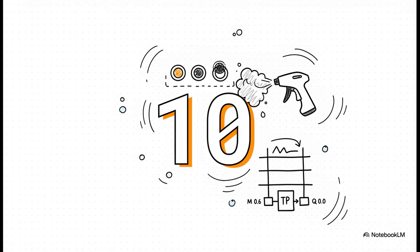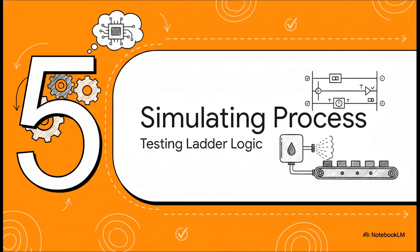The massive advantage of using a timer pulse here is that once it gets that trigger from M0.6, it immediately turns our output on, our nozzle at Q0.0, and keeps it forced on for exactly 10 seconds, regardless of what the user does with the unlock button afterwards. They could press it 50 times, it doesn't matter. Once those 10 seconds elapse, Q0.0 shuts off, the nozzle stops spraying, and the area is perfectly sanitized. Section 5. Simulating the process.